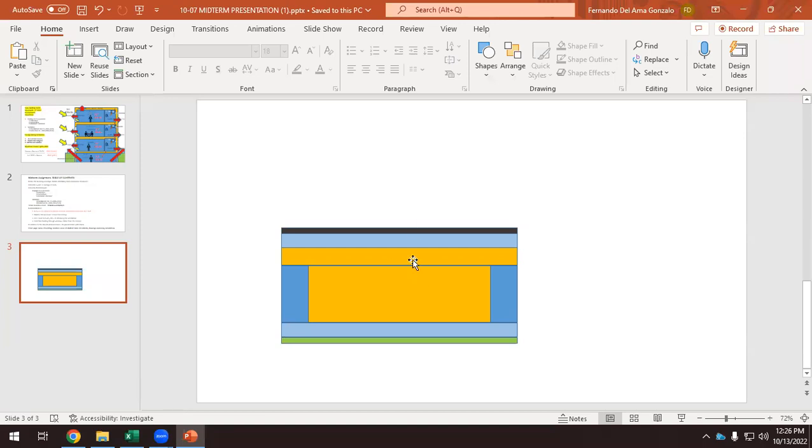The other option would be to place this thermal insulation underneath the existing ceiling. But with this option, you are losing free height. The minimum free height is 10 feet. So if the ceiling is at 10 feet above the floor level, you cannot go below that because the minimum has to be 10 feet. Okay, so if you have high ceilings, probably you can do that. You can apply the thermal insulation indoors. And working indoors is always easier and cheaper because people working indoors, first, are safe.